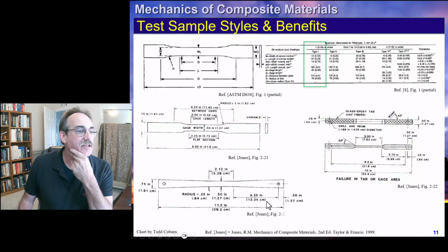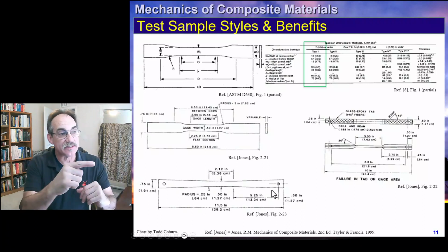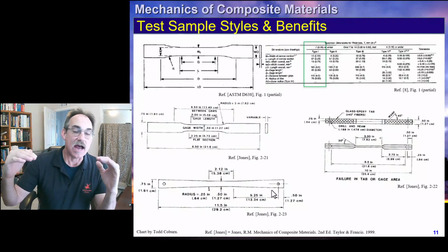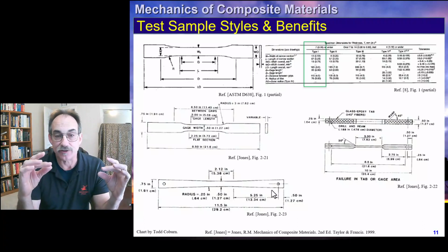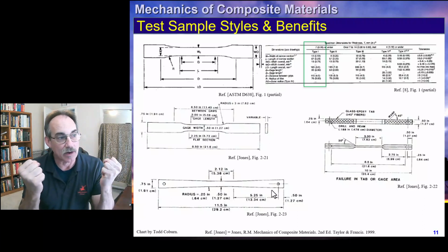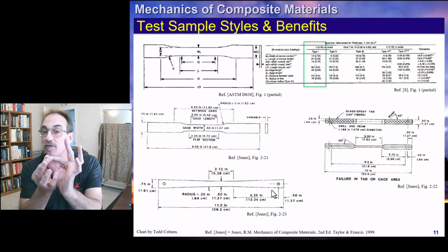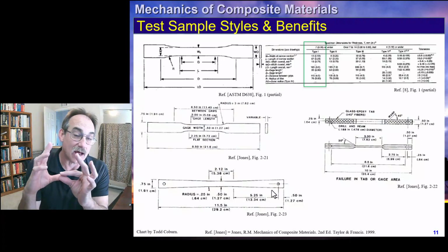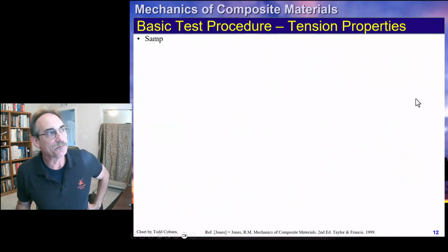This one, sometimes called a bow tie sample, you'll notice that it's a lot softer. It's more carefully designed. This can be harder to make well, and you've got such a long region, but this will do a better job of eliminating the stress risers. You'll notice because this is loaded, instead of grabbing it with grips, it's got holes to load with a punched through element. So now you've got to be careful for bearing and tear out failures at the edge, which means it's going to probably have to be either a lot wider or a lot thicker out here at the edges for that kind of sample.